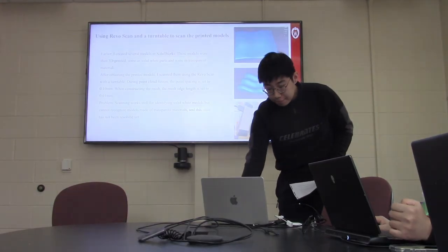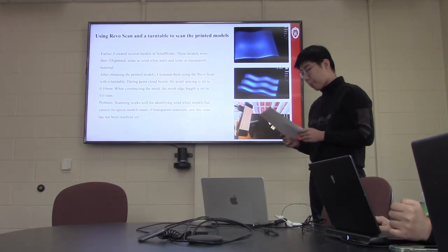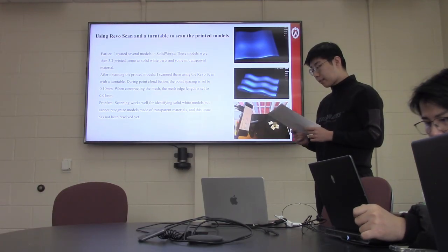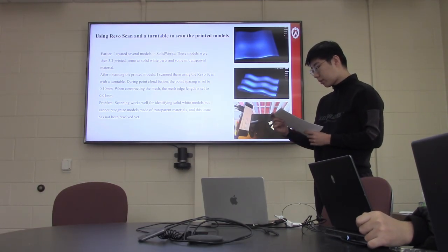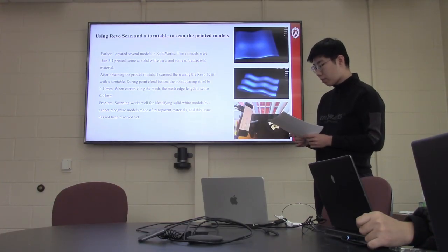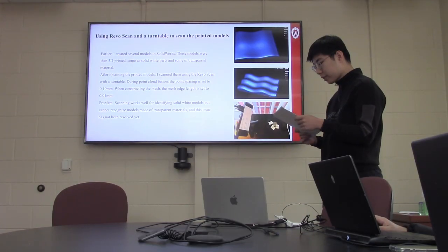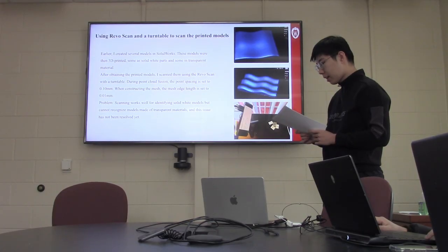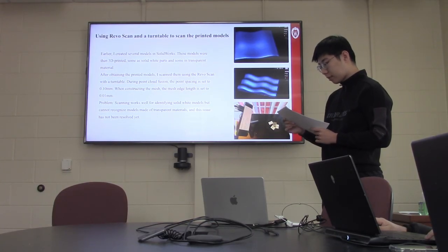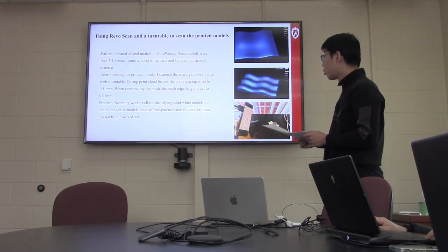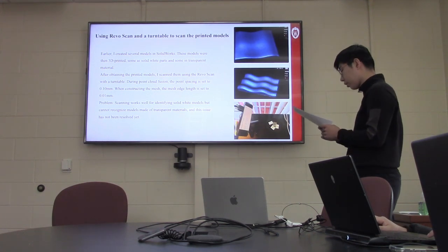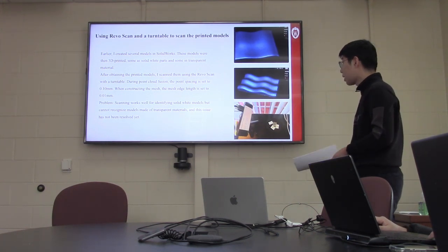After creating these physical models, I scanned them to see how well we could capture their shapes. I set a fine resolution, about 0.1 millimeters point spacing of the point cloud, and generated a detailed mesh with roughly 0.01 millimeters edge length. The scans of the plastic models came out nicely, giving me accurate digital versions of those surfaces. However, I ran into trouble with models made of transparent materials. The scanner just couldn't pick those out well.